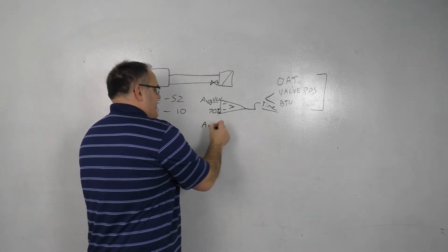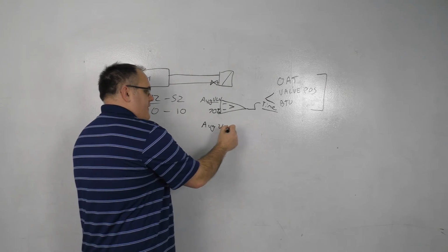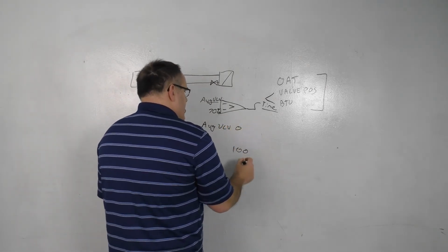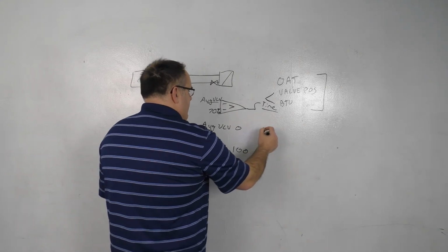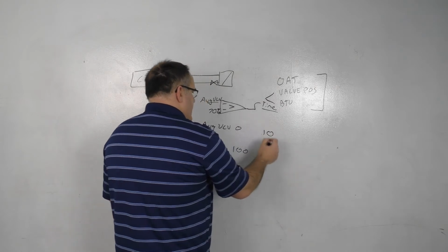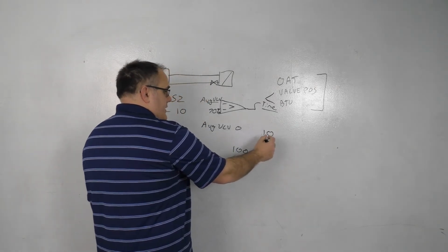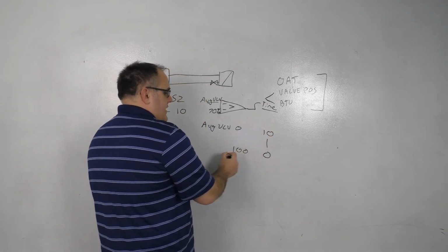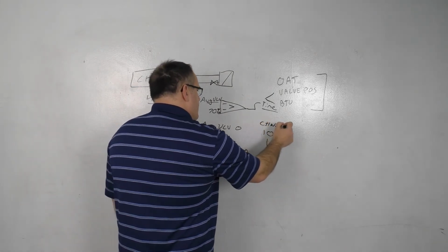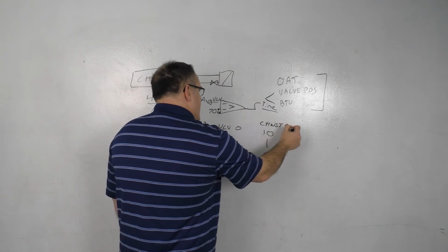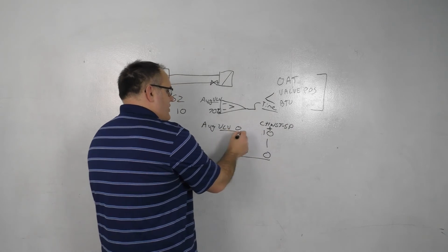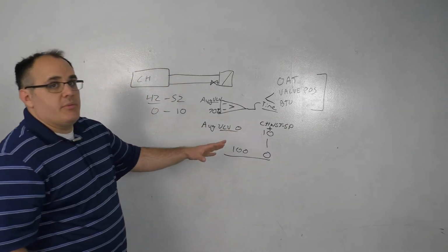You can have average valve, and that can be 0 and then 100, and then you reset from 10 to 0. And that is in addition, so this is an upwards reset right here. You reset your chilled water supply temp set point, and you're adding. So you add 10 when you're at valve 0, and your range would probably be a little broader.